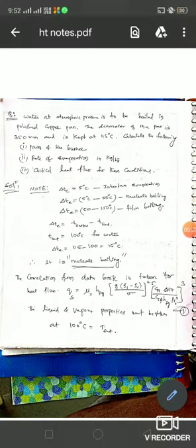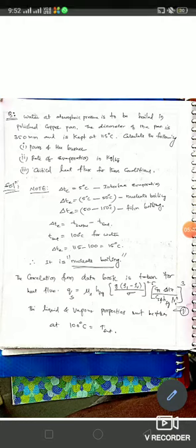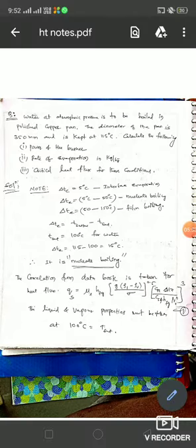The excess temperature is delta T E, surface temperature minus saturation temperature. If it is below 5 degrees Celsius, that will come under the interface evaporation zone. If the excess temperature is between 5 and 50 degrees Celsius, it is nucleate boiling. And 50 to 150 degrees Celsius is film boiling.